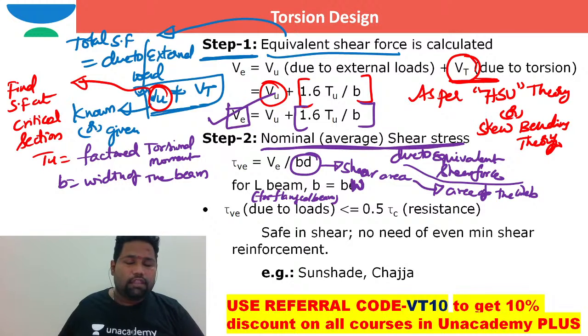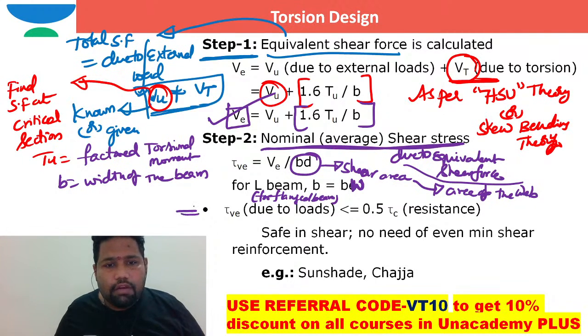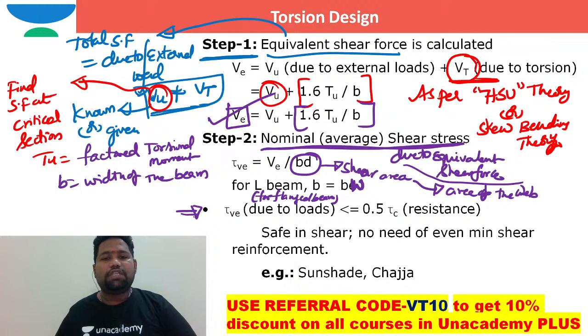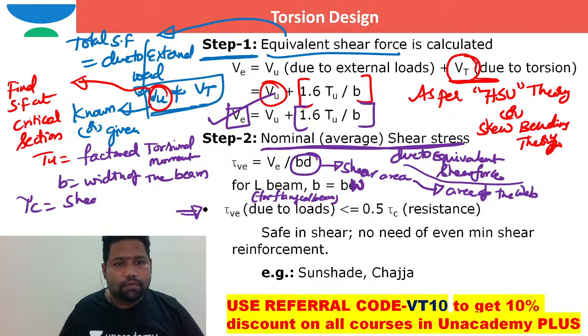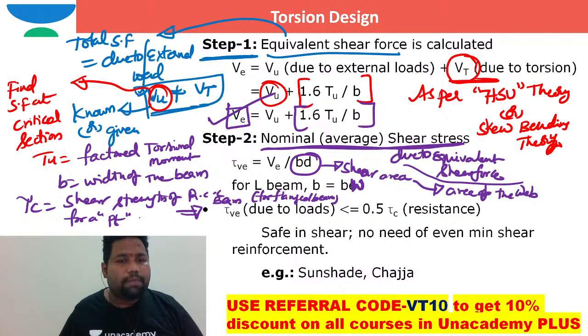So for tau, there are three conditions. Condition number one: when tau V, that is the nominal or average shearing stress due to loads, is less than or equal to 0.5 times tau C, the shear strength of the RCC beam. What does tau C stand for? It is the shear strength of the RCC beam for a desired percentage of tension steel and fck.